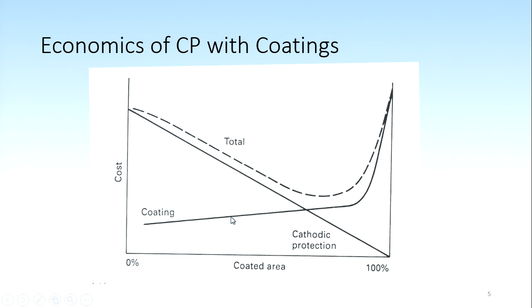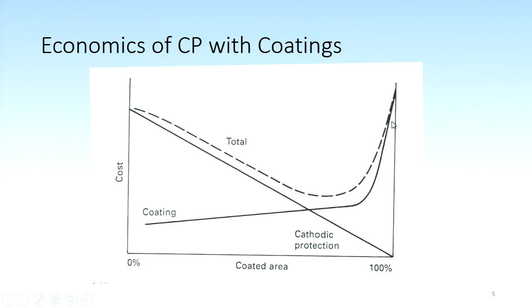What of course happens with your system is that if you plot current against time, then as the coating degrades, the current goes up. So you'll start off probably with a fairly low current, and it'll begin to climb with time as you get more defects in the coating.